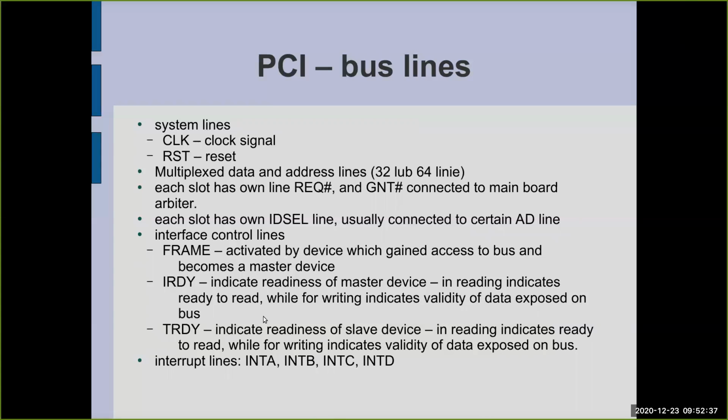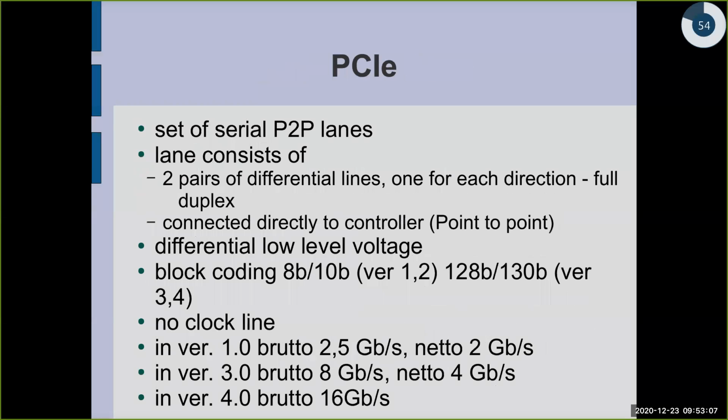There were interrupts. So the mode in which devices on PCI were handled used interrupts, not polling. But we have only 4 interrupts, so they were shared among the devices. If we have more than 4 devices, special groups were created.